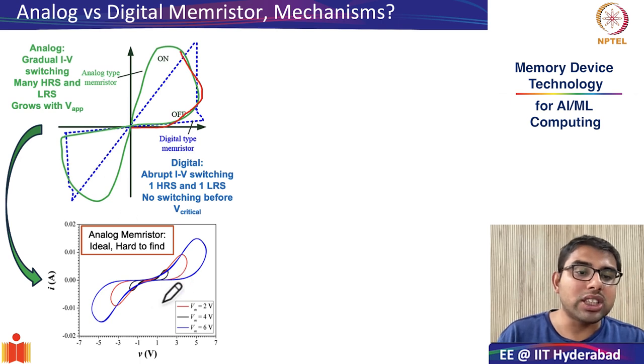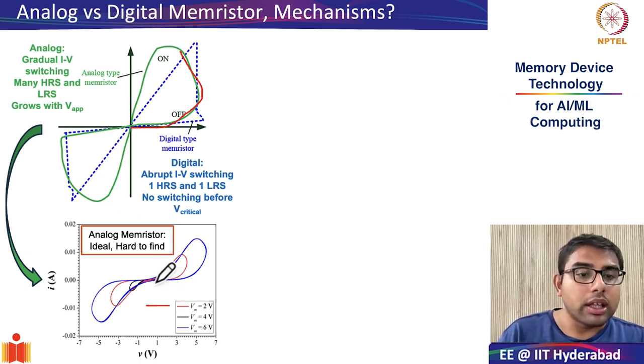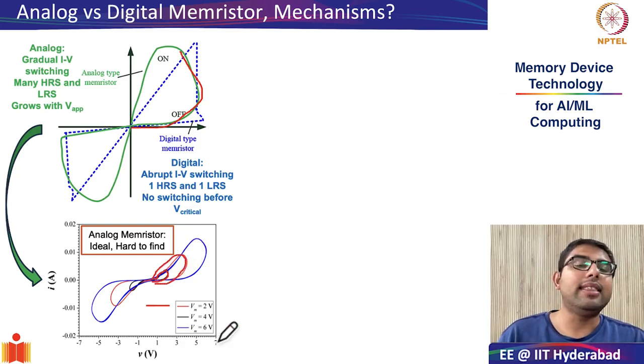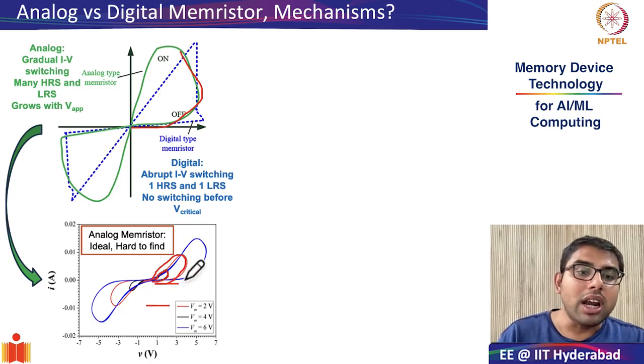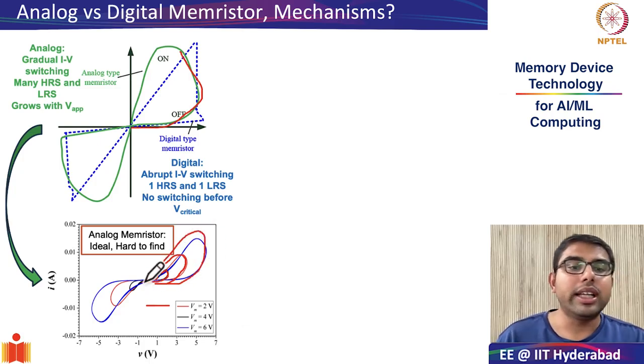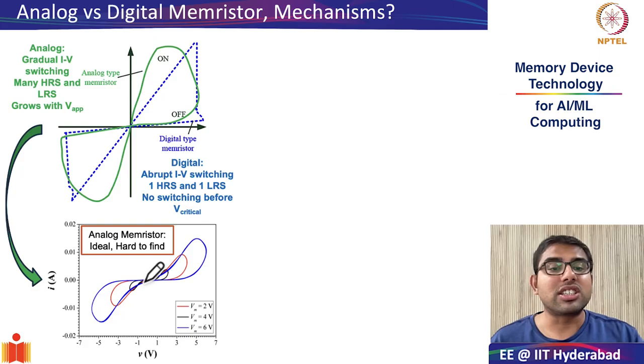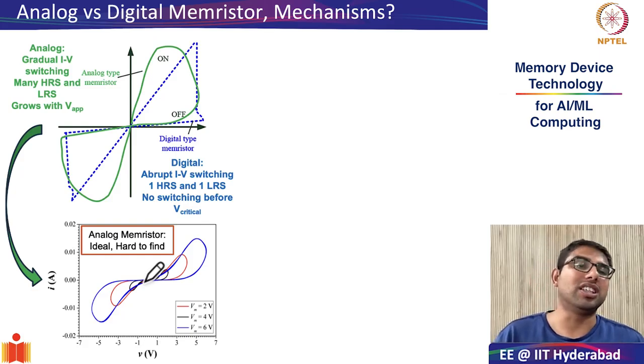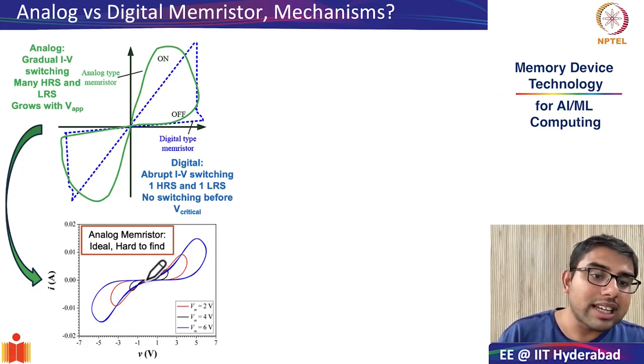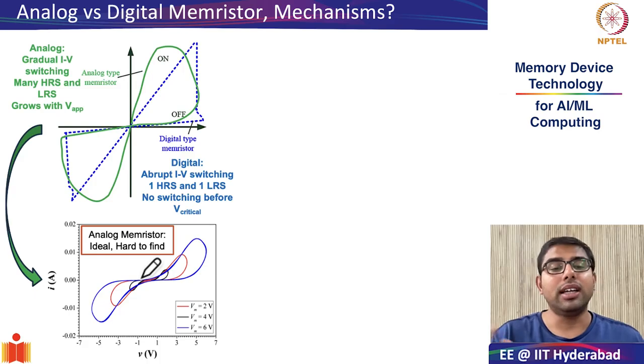That is shown in this particular diagram below. In this diagram, you see that by cycling the device through different stop voltages on the x-axis, you can keep expanding the size of the hysteresis or the pinched loop hysteresis. And of course, the hysteresis can be corrected back by cycling in the opposite direction.